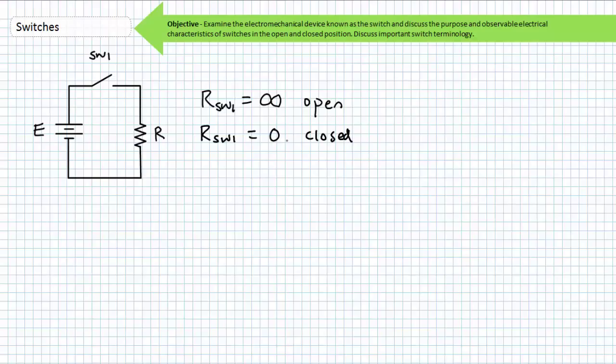Given our understanding of the most fundamental of series circuit properties, that current in a series path is the same anywhere in that path, a switch in series with an electrical device is an incredibly important application of this principle. If there exists no current flow through a device in a series relationship, there exists no current flow through the whole series relationship.